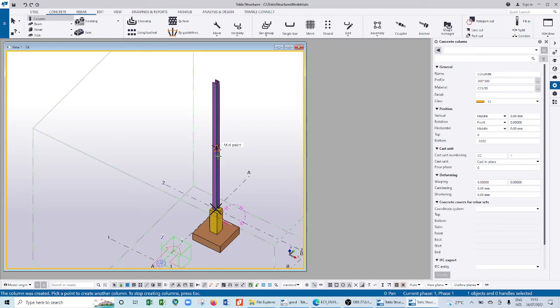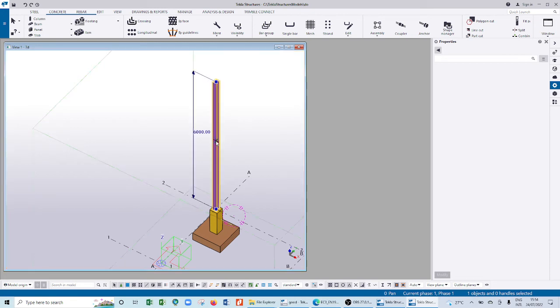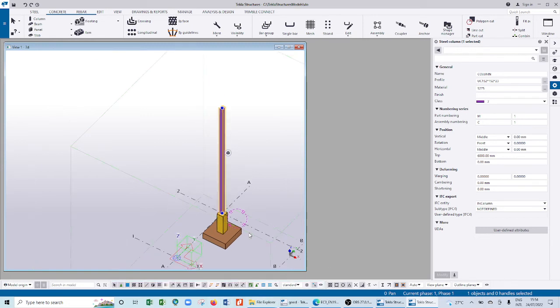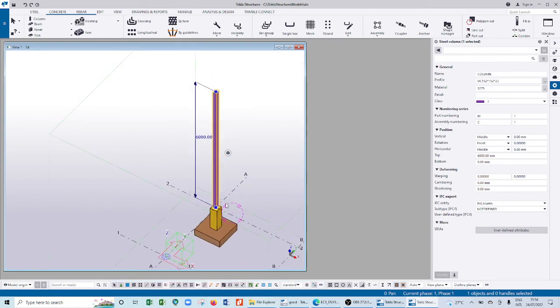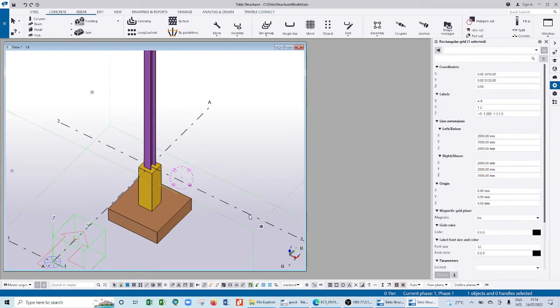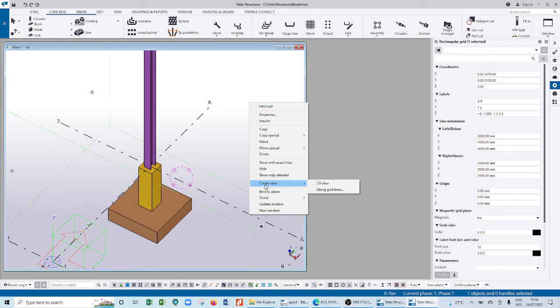So the same thing, the way I've done this column, after you've done one, if you want to draw those other one, you will just go and highlight and say, I'm going to draw for the next one, using the same thing I have. Then I connect the beam and take it for detailing, then we summarize. So once I have this, I go to where there is a grid line, double click on your grid line, then right click on it.